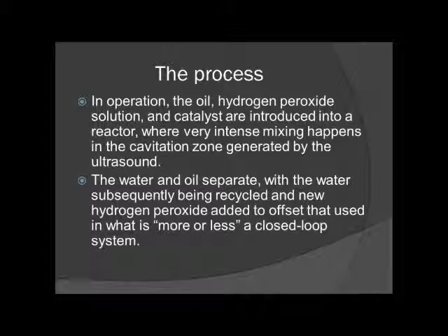For the process in operation, the oil, hydrogen peroxide solution, and catalyst are introduced into a reactor, where very intense mixing happens in the cavitation zone generated by the ultrasound. The water and oil separate, with the water subsequently being recycled and new hydrogen peroxide added to offset that use, in what is more or less a closed-loop system.